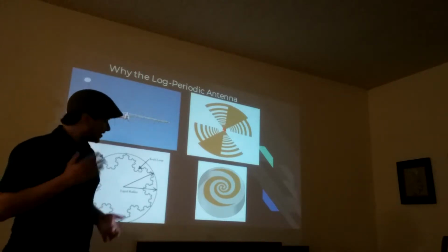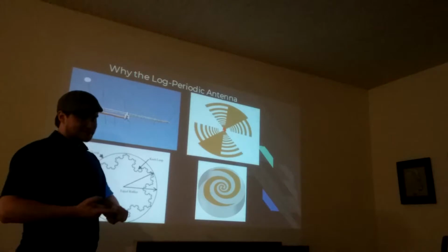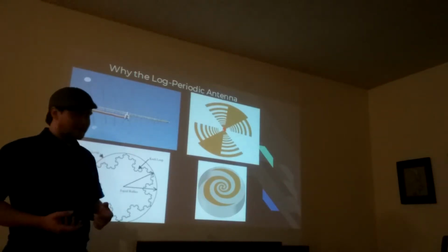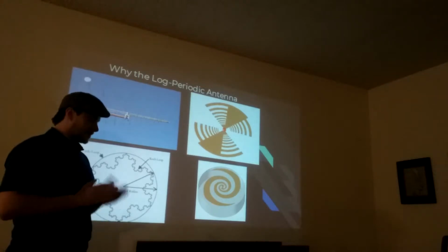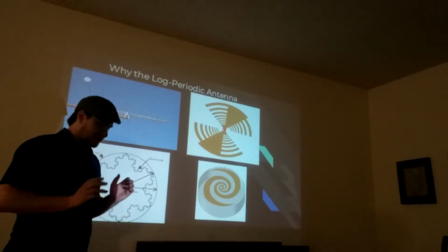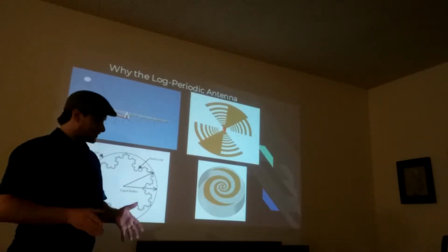So to me what that meant was that they would have a constant impedance across a large band of frequencies, and I would be able to design an antenna that would be relatively small and easy to match to, so it fit all of my design criteria.